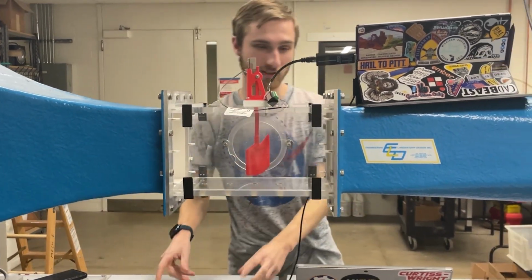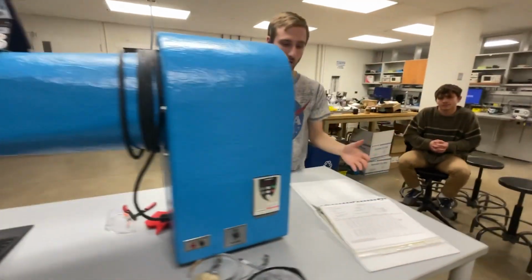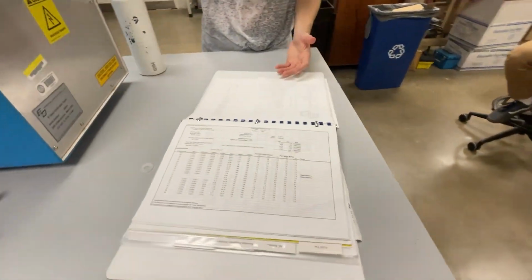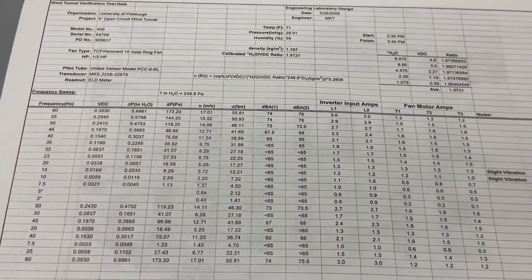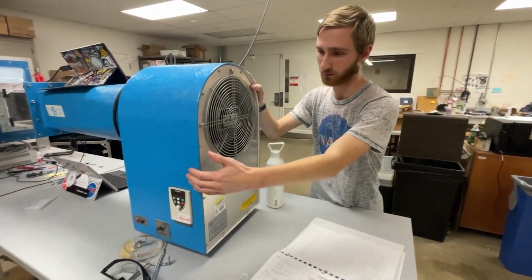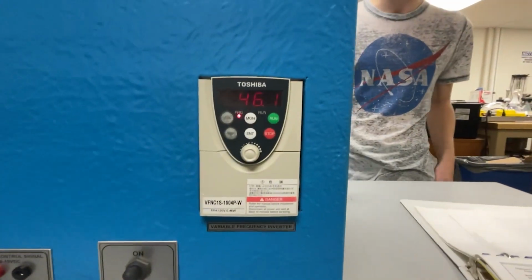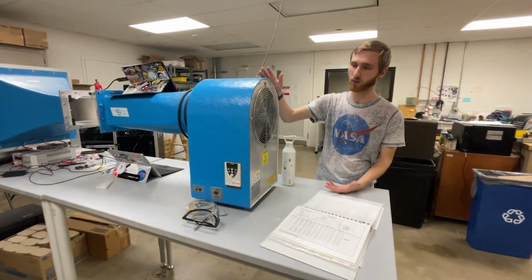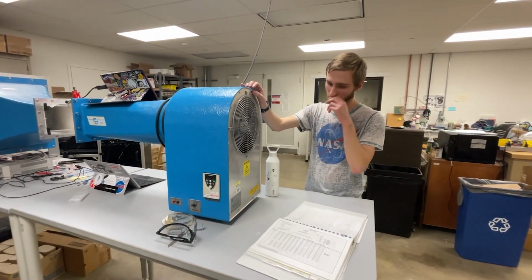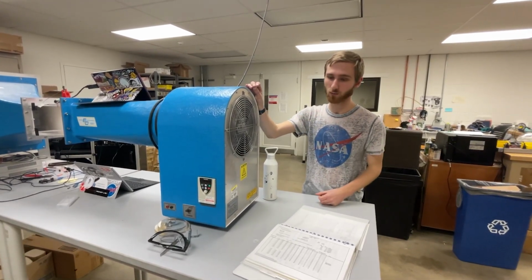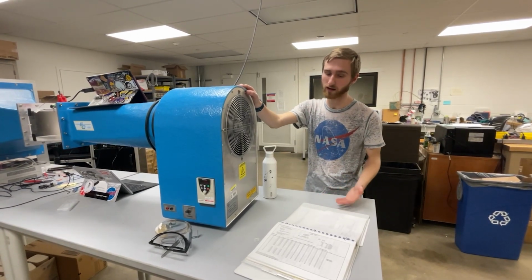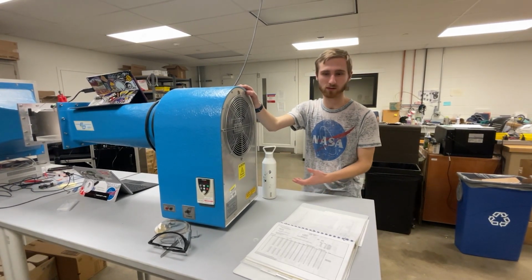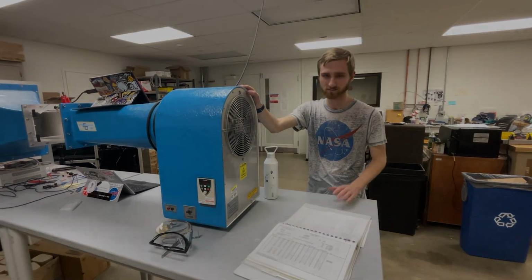But what we used instead was just the calibration from the actual wind tunnel itself. So there were calibrated values from a while ago that basically allowed us to determine what the actual velocity in this was as a function of the frequency in here. So that calibration was pretty similar. Again, it used basically a pressure sensor in here to find the velocity in the same way. When it's at essentially zero, you have nothing flowing through, you know that it has to be reading zero velocity, so you can sort of get rid of that same bias that way.